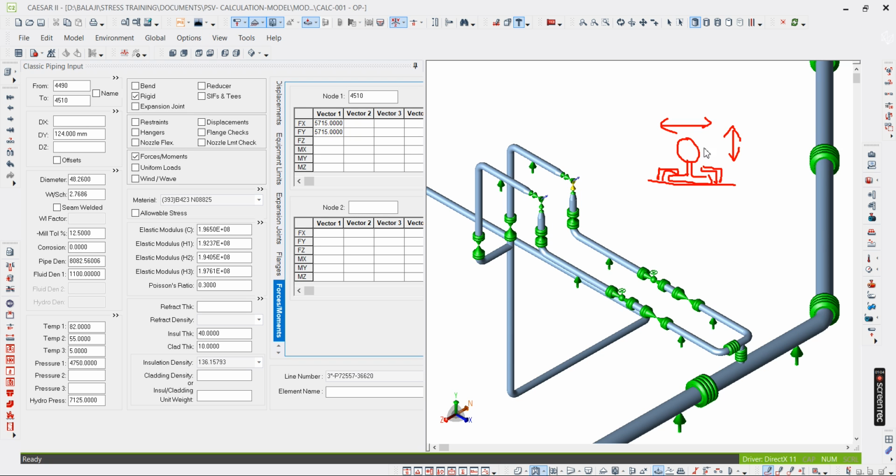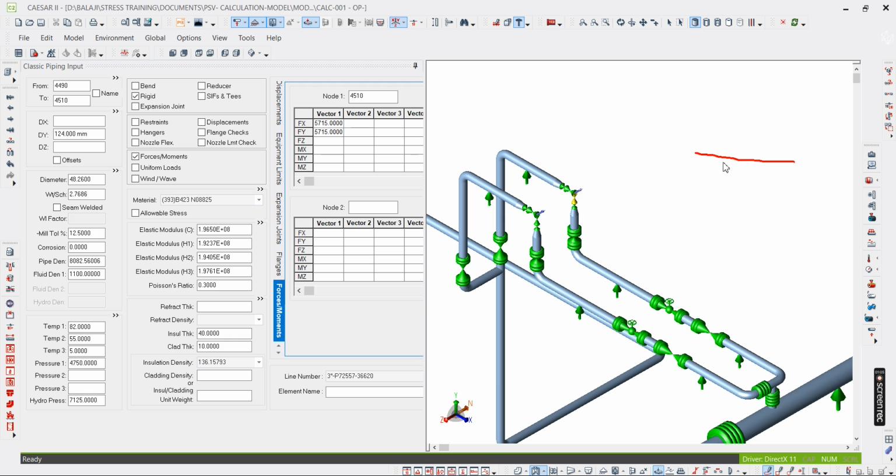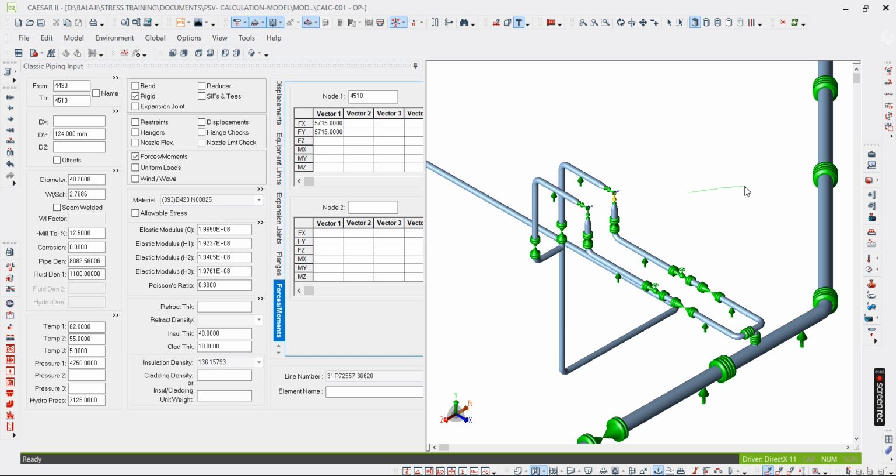Okay. So in this case, since this is a vertical pipe, we have a hold down arrangement. I will show you that one. And at the outlet, you have to provide limit stop. Limit stop is nothing but axial stop or limit stop. So this is a shoe. I am just giving the idea. So the arrangement may be different also. That depends on your support standard.